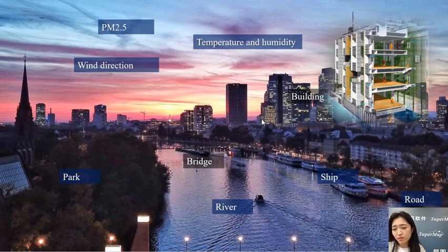A large amount of BIM data is accumulated during the design and construction with BIM technology, and it can be used as an important data source for 3D GIS applications. Compared with 3ds Max model data, BIM model data is more refined and accurate, and has complete semantic and attribute information, which can meet the needs of refined management in GIS applications.